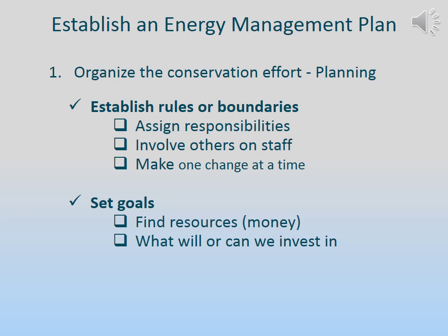We should ask at the plant or talk to some experts about how long that type of probe lasts. We know plants that have probes, and some have replaced them 1 or 2 times a year. It is hard to believe that can be paying for themselves under that scenario. There is not an endless life to these devices, so we need to somehow determine the useful life for that measure we came up with. Again, if it is an ammonia or nitrate analyzer, what is its useful life?